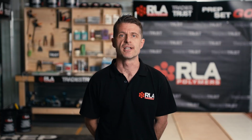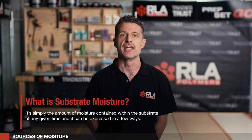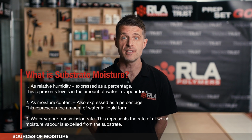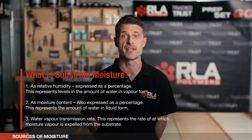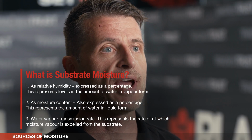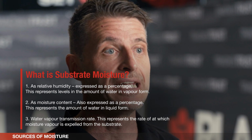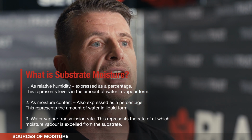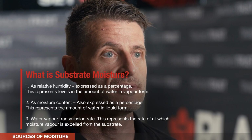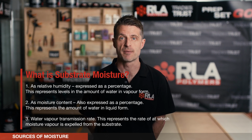So substrate moisture, what is it? It's simply the amount of moisture contained within the substrate at any given time. And it's typically expressed in two ways: one, as relative humidity, expressed as a percentage, and this just represents the levels of water vapor in the substrate. And two, as moisture content, which is also expressed as a percentage and represents the amount of water in liquid form. Now there's also a third consideration, which is important when it comes to certain floor finishes, and that is water vapor transmission. And this represents the rate at which moisture vapor is expelled from the substrate.